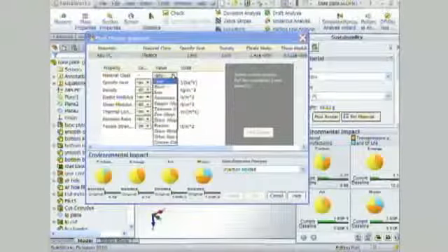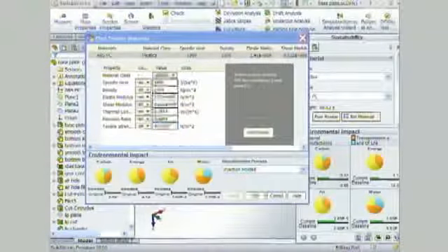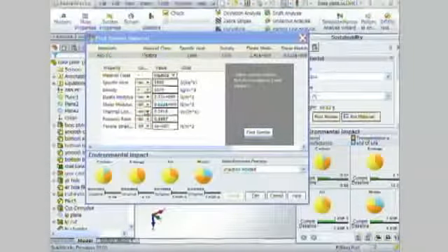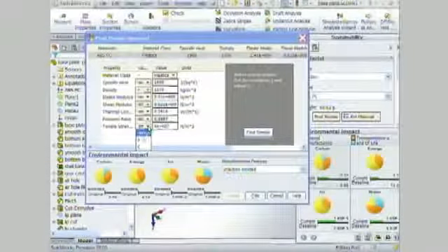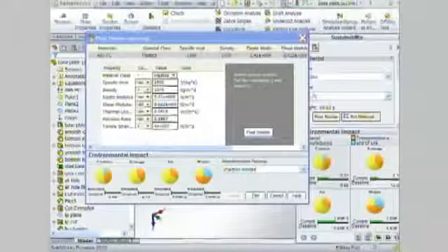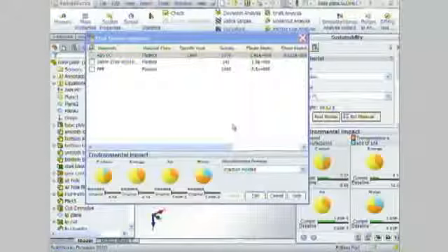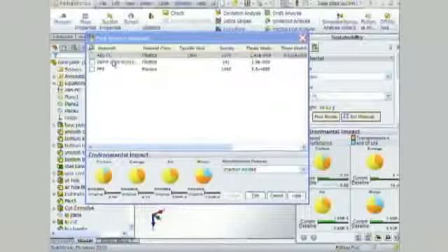So I'd like this next material to, again, be a plastic. I want it to be lighter than the current plastic that I'm using. And you know what? In tension, I want it to be stronger. And then we'll have the system search the database based on those mechanical priorities. And instead of having 30 materials to evaluate, I have 2 that I know meet my mechanical requirements for the design.